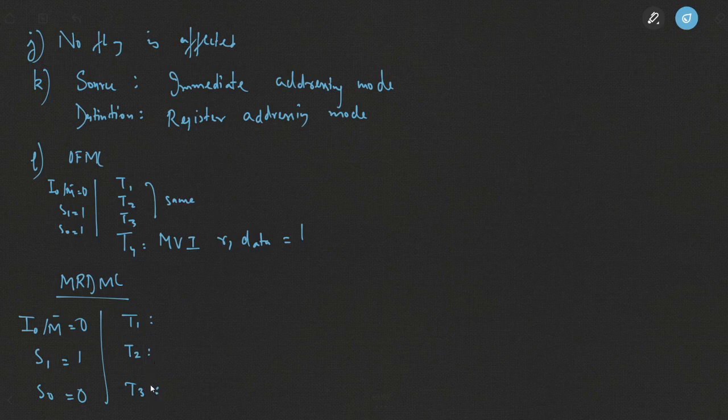Fine. Now see the difference here with the 2-byte instruction. That means in the opcode fetch machine cycle, the program counter is already pointing towards the next memory location, and at the next memory location, what is there? At the first memory location, the opcode is there, the opcode of MVI. Fine. At the second memory location, what is there? The data is there. In the previous three instructions, we were having only single-byte instructions, so it was only occupying 1 byte of space. Fine, this much space. So the program counter in the T1 state, in the opcode fetch machine cycle, we were already incrementing that program counter, and it was already pointing to the next location. What was happening previously in the last three instructions, I'll show here.